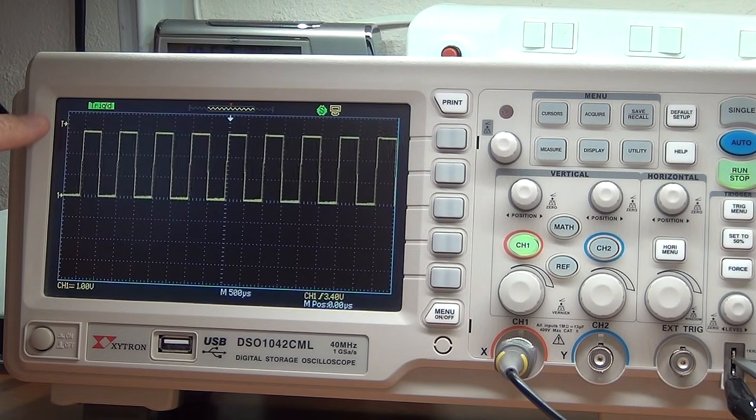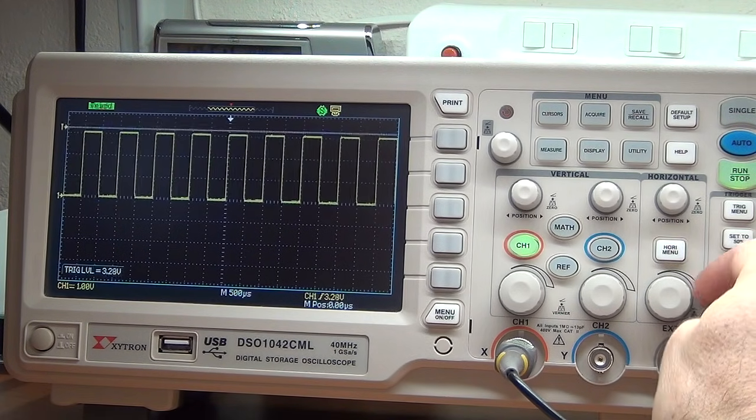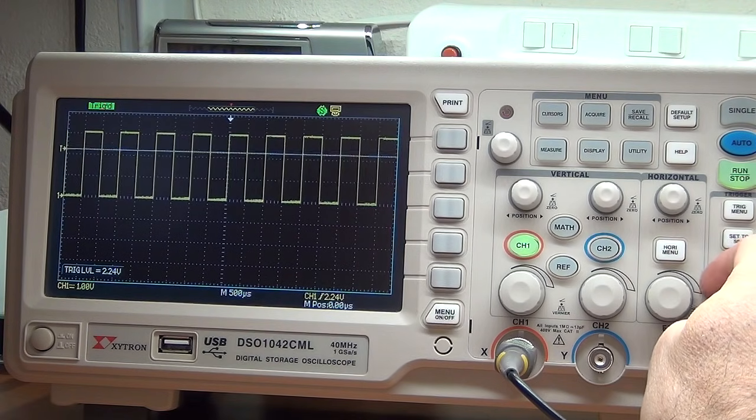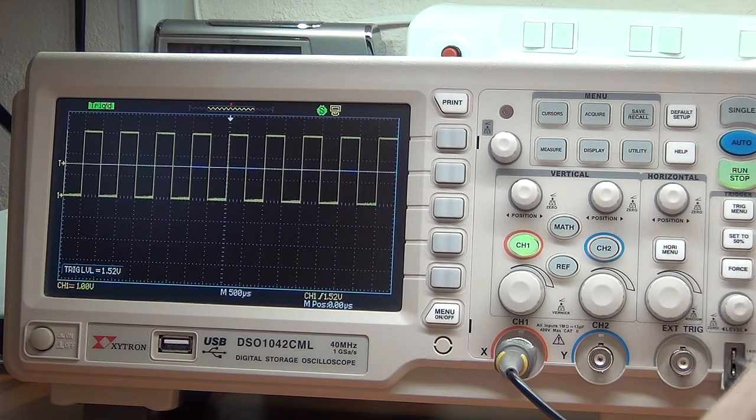So there's a trigger point which can be set to stabilize it, and if you set it in the right place, it will stabilize the wave. Over here on this oscilloscope, there's a knob which you turn down. As you can see on the display, there's a line which comes down, and as I move that down so the trigger point is right in the signal, you can see how you get a nice stable waveform on the oscilloscope.